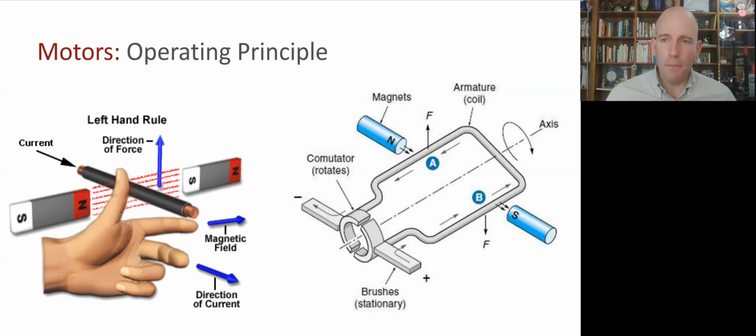Now there's a matching effect, which is that if you take a wire and you move it quickly through a magnetic field, that tends to cause the electrons to move. There's an electrical potential pushing the electrons. There's a voltage. And the magnitude of the voltage, again, will depend on the strength of the magnetic field, the length of the wire, and how fast the wire moves. And that is why this back EMF, or this electromechanical voltage drop in your motor, is proportional to speed of the motor.